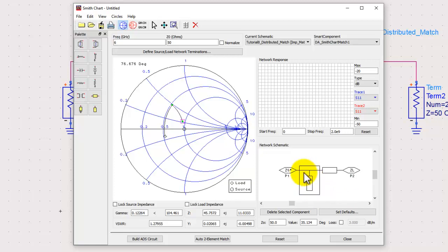Now again, this open circuit stub, the impedance by default is 50 ohm. However, to make it more capacitive, let's say here with 50 ohm impedance and 35-degree electrical length, which if you want you can convert in lambda, is taking your point from this point to this point. Now what if we make it more capacitive, and how do we make any line more capacitive? Is by decreasing the impedance. That means we make lines wider, and by putting 20 ohm, and you can see suddenly now with the same amount of electrical length you can get much bigger impedance transformation.